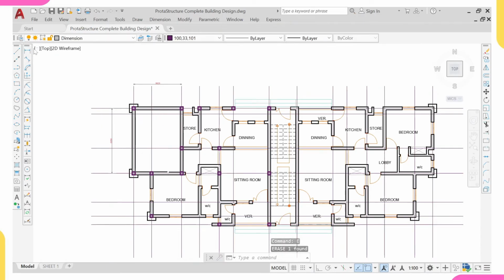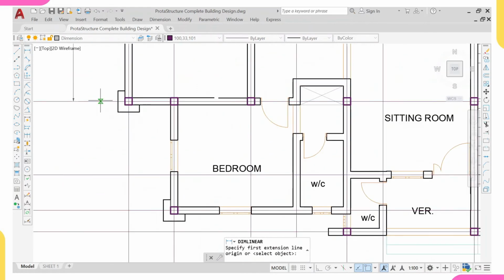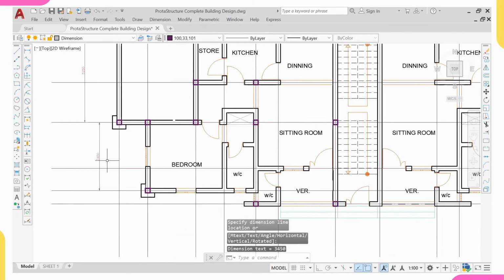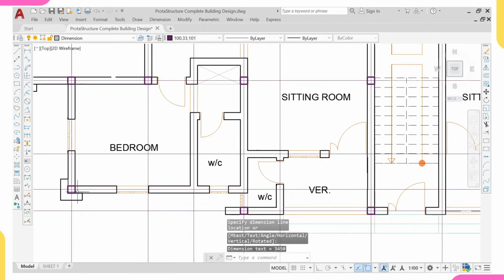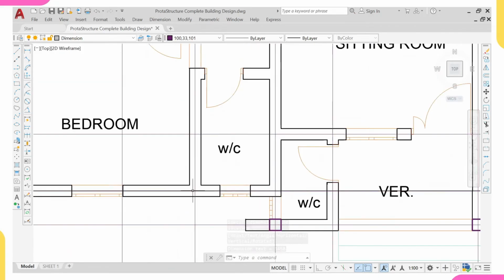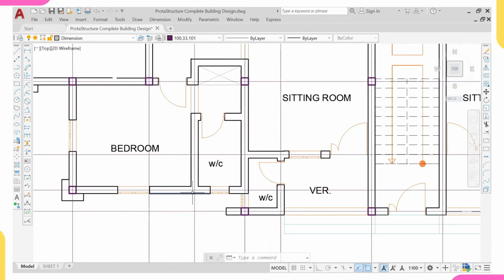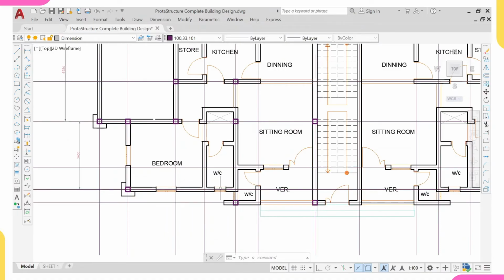Hope you understood. So I'll click on this and check from this point. I want the whole of here, both this bathroom and toilet and bathroom, to be under one panel. As people that don't know anything about structural design, they will place a column here because they are seeing a wall here. They will place a column here and also come and place a column here. And if you are placing a column here, you'll be having 2Y16. But since I've decided to have the whole of this length as one beam, the probability of you having 3Y16 has increased.